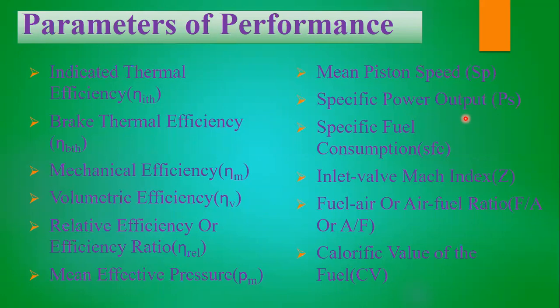A reciprocating motion is one thing, but a heavy piston also absorbs energy and makes it hard for the combustion gases to push it downward. So we need to reduce the piston area as much as possible, which increases the specific power output. It's just a brief; I will tell you more later about specific power output.